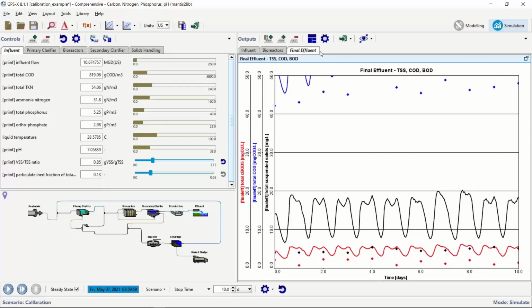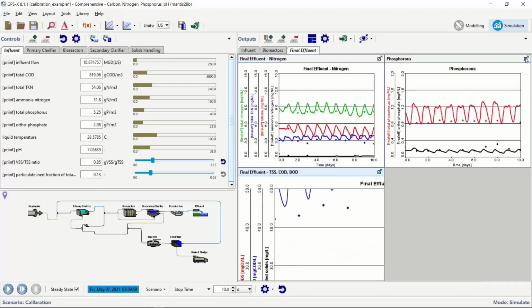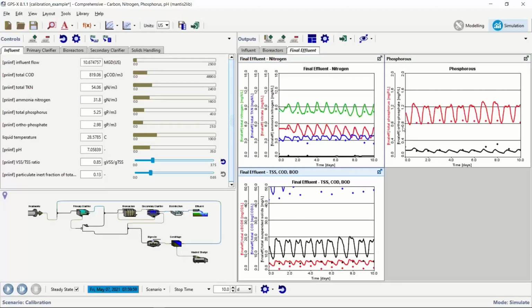So that's probably the next place. Start with your influent, look at your mixed liquor, and now let's look at our effluent and see what we can do. I think in this case, because it's pretty much straight up solids, that is the problem. If I remember correctly, you can see here that our effluent soluble phosphorus is okay. It's the particulate phosphorus that's the problem. Okay, so we've got too many solids here.